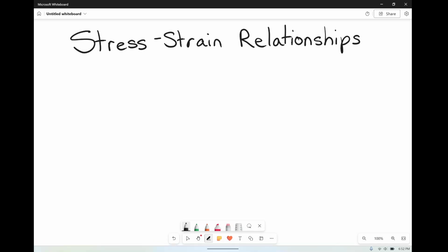This video is going to cover stress-strain relationships and how to use the equations that we covered in the stress-strain diagrams lecture. So we actually only had 3 equations, really technically 4 if you want to consider that modulus of rigidity had 2. But we start off with modulus of elasticity, that's E, is equal to stress over strain. This is normal stress over normal strain.